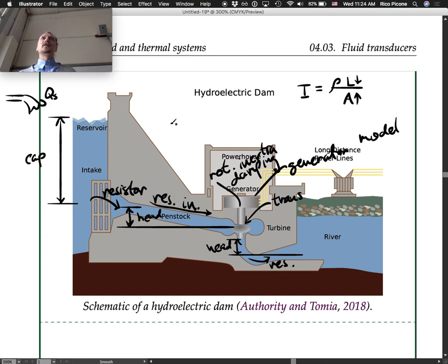In a model that you're really concerned about all of the details with, you might want to include it in any case. But a lot of times we won't include it unless this parameter is significant. So you can always compute it and try to get a feel for it. And a lot of times the way to go is to say, okay, is this significant in comparison to other inertances in the system? Like maybe it's a factor of 300 smaller than any of the others. You say, oh, okay, we probably don't need to worry about it. That type of thing. But it is a judgment call.